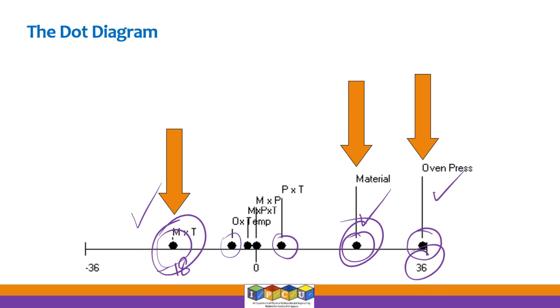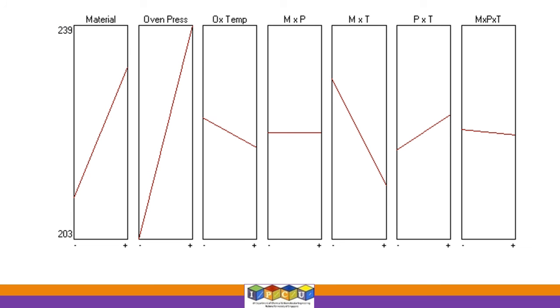So again, like everything, process gain or process sensitivities or these effects can be double-edged swords, right? Sometimes they can help you, and sometimes they can work against you. Okay, so that is the idea. These numbers, the effects, what we call as effects, 36, 22, and -18, they are nothing but sensitivities or the process gains, and we can choose to manipulate them.